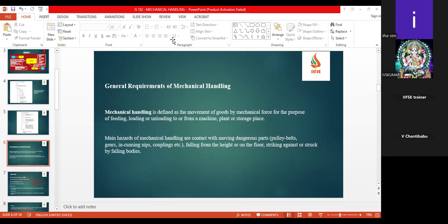They do only the visual inspections, but I have seen somewhere in the Indian standard that even the crane hooks should undergo UT to see internal cracks, because over a period of time, there will definitely be a formation of cracks in the hooks.